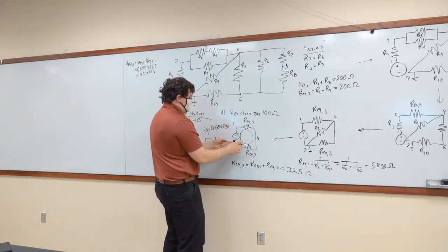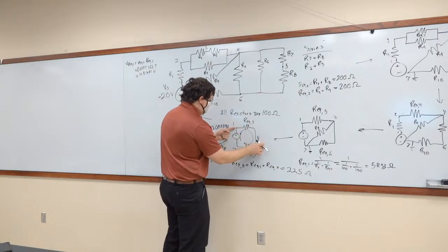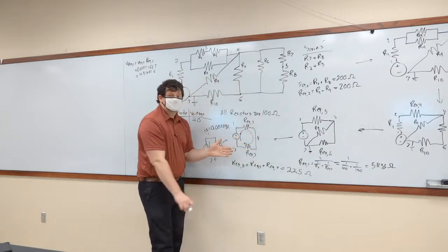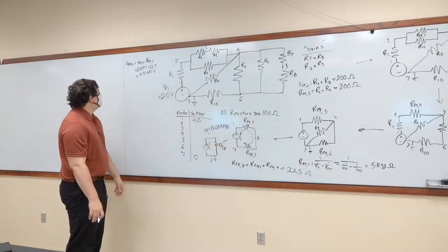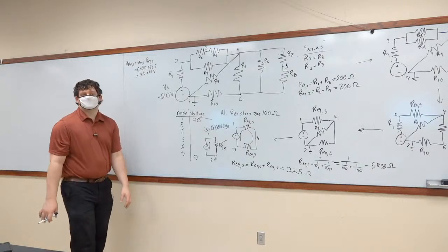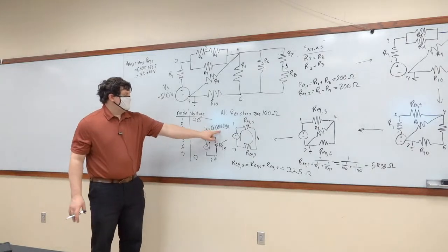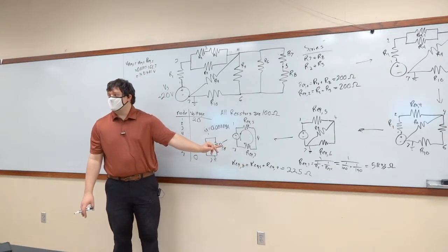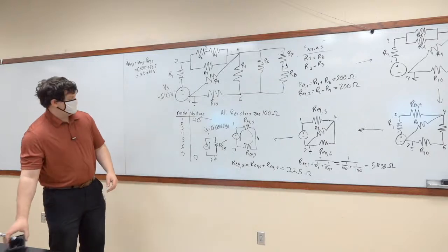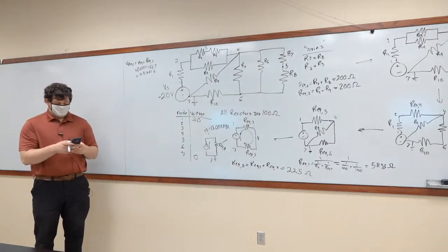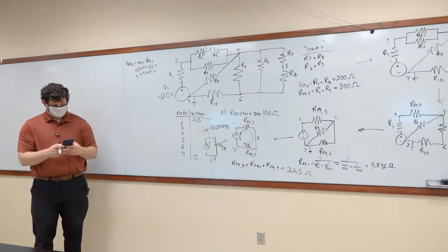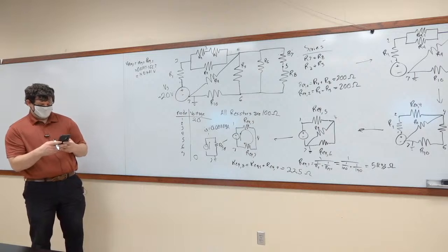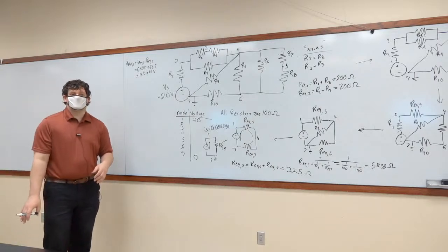An electron coming up through the battery starts at 0, gains 20 volts, loses 14.81481 volts, and then across here that means it should lose 5.185185 repeating, right? Well, if we take 0.08888889 and multiply it by REQ7, we should get 5.185 repeating, right? Why don't we do that, just to check our math. REQ7 is 58.3 repeating. Multiply it by it, you get 5.185 repeating. So we did something right.